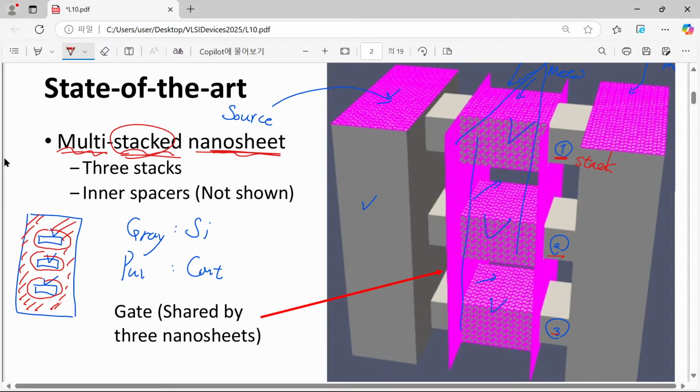Yes, we understand this. They are nanometer scaled, and sheet means that when we first introduced this technology, the cross section was not ideally like this. This one is a cross section. Here we have, for example, roughly 5 nanometers thickness, and the width, if that is the smallest, corresponds to 10, and we can even have a much wider one, 20, 30, 40.